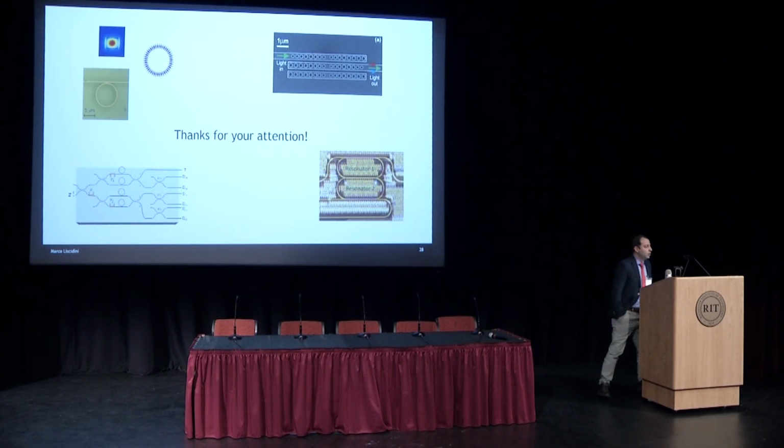Thank you. Okay, so the main problem with photonic crystals, in my opinion, is the design first. Even the strategy that I presented of linearly coupled resonators is actually very difficult. When you fabricate these devices, it's not really true that you can get identical resonators. And at the end of the day, the splitting is not always sufficient to have three equally spaced resonances. So I think this is a topic that is worth investigating with, for example, a genetic algorithm.